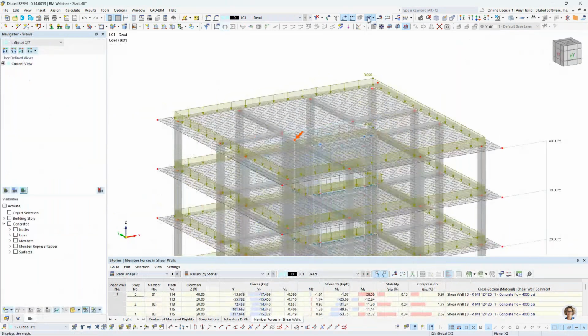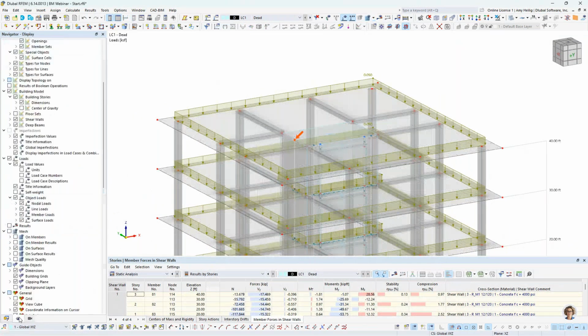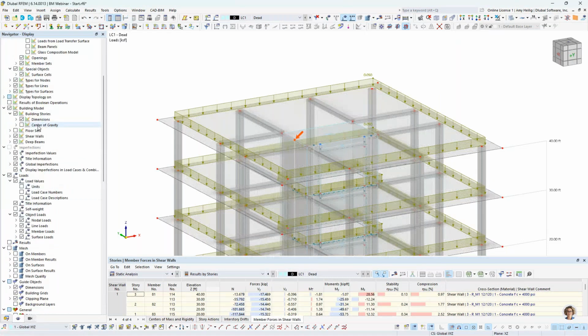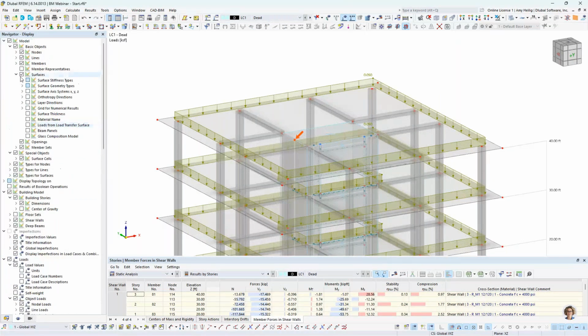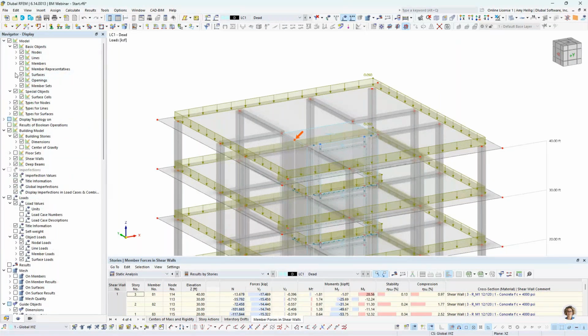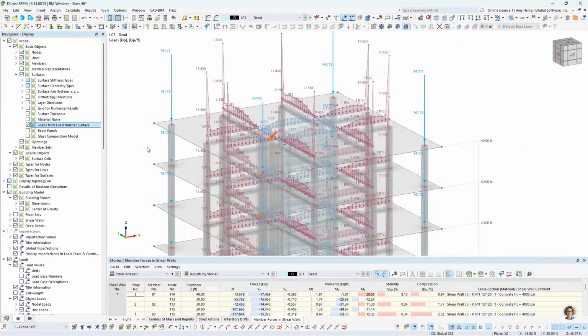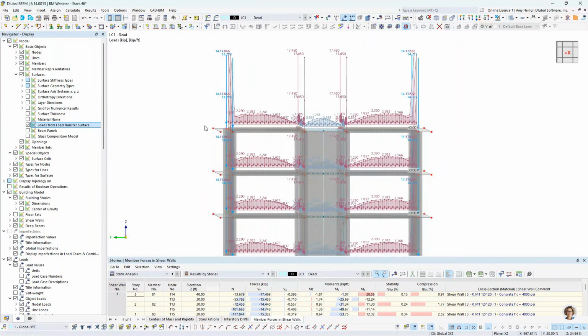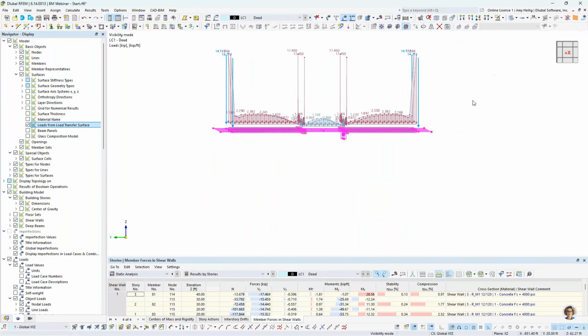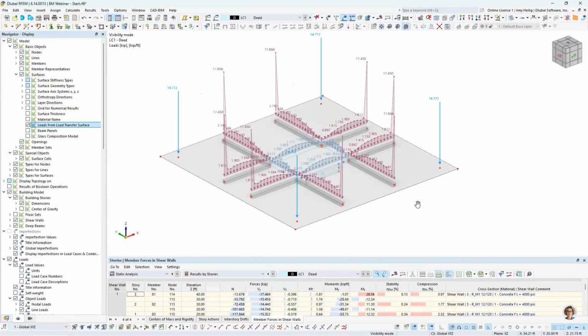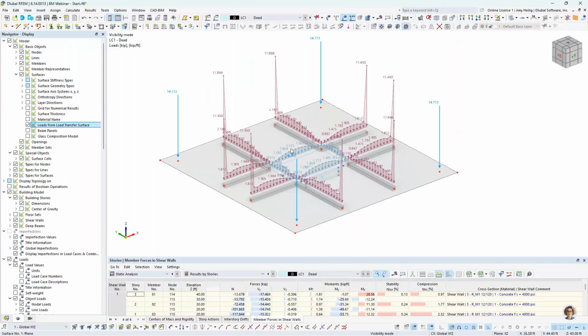I'm going to go ahead and turn off the display of my FE mesh, and under my viewing options at the project navigator, if I expand here all the way at the top under my surfaces, I have the ability to convert these loads to load transfer surface to see exactly how they're going to be distributed. So again, this is what the program is doing internally, and I'll go ahead and create a user-defined visibility here for only these elements with the FEA option. So very detailed here in how these loads are going to be distributed to the objects.